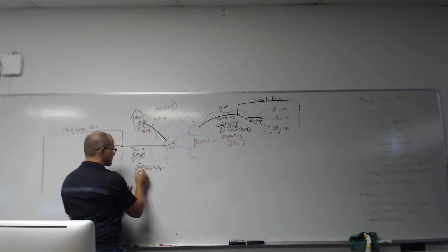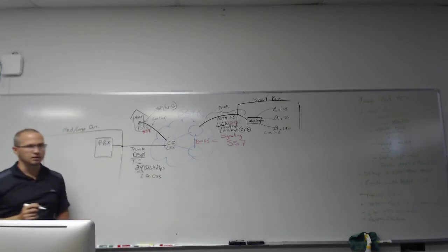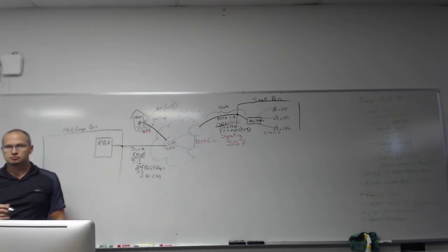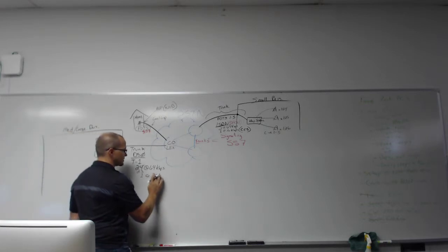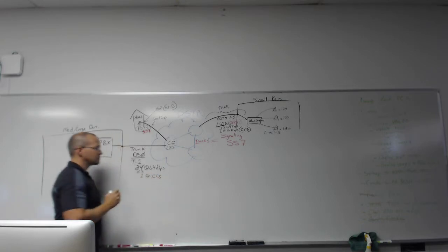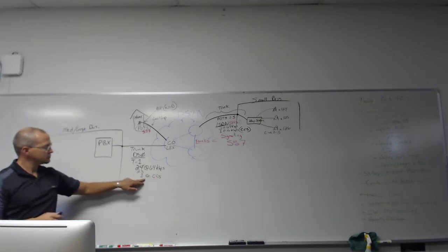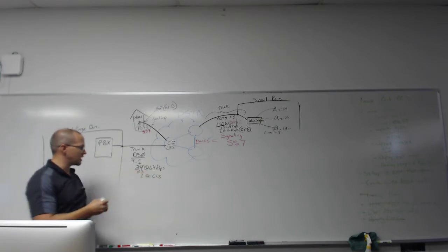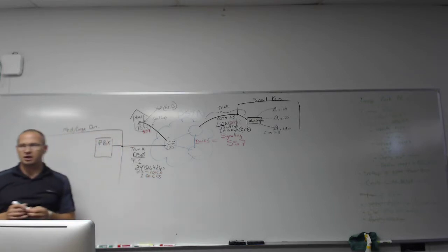So that means we have 23 because we have the one channel dedicated for the CCS, for the signaling. No, I'm being dyslexic here. It's not CSS, it's CCS. Common channel signaling. So with the T1, we can have 23 voice channels.